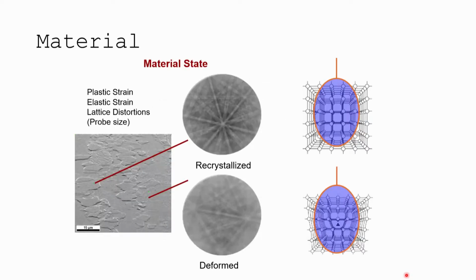All right, so quick on diffraction: how does this affect pattern quality? This is what we're going to go into now. There's a lot we can talk about when we talk about quality of EBSD patterns, and one of the first things is whether it's a deformed crystal or an undeformed crystal. Why does that matter? One example is a dislocation, this is just a simple edge dislocation in the crystal. All of a sudden you have planes that aren't in the right positions anymore, and these atoms aren't in the right position. So the Bragg condition for diffraction changes locally, and as soon as that changes locally, you get a decrease in diffraction intensity. If it changes enough, you get a complete extinction of diffraction.